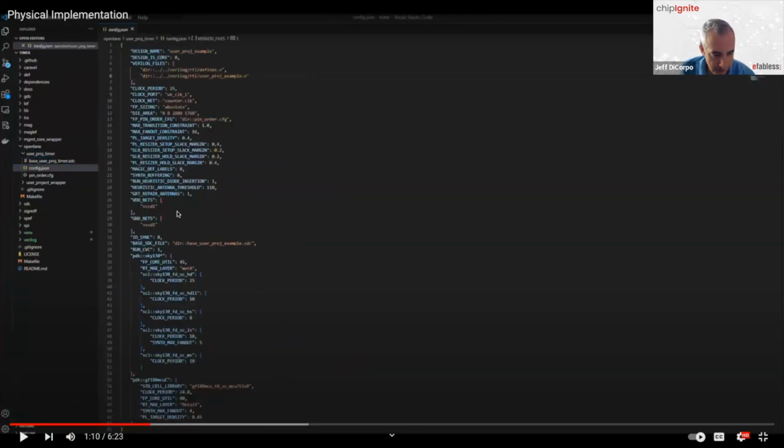So just to give you a note here, the template provides an example configuration for implementing a macro, which is what we're leveraging here. It also comes with a base constraints file that would be sufficient for many designs that are just dependent on the core clock, that are using the wishbone or the core clock within Caravel.